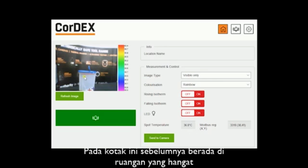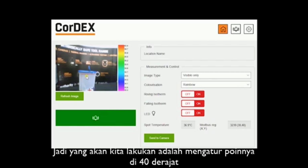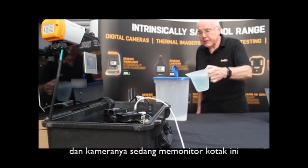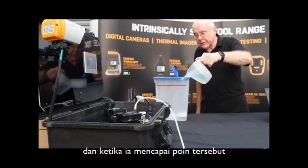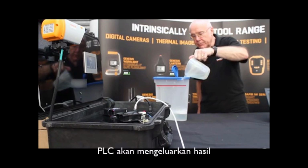And this particular container has been in a warm environment, so as you can see the temperature is reasonably high, 36, 37. So what we'll do is set our set point at 40 degrees, and the liquid pouring is at 48 degrees, so there's a good differential, so that will be okay. I'll now pour the liquid in, and the camera is now monitoring this container, and it is looking for a line thermally, and when it reaches that point, the PLC will initiate an output.